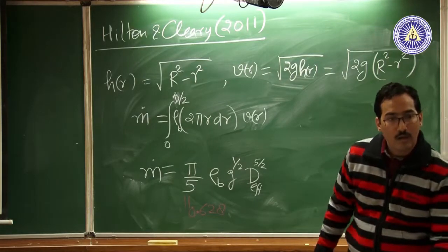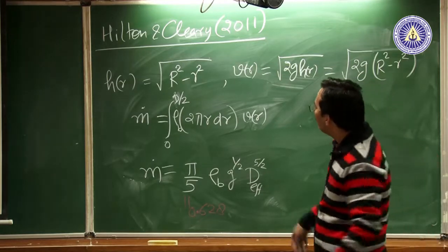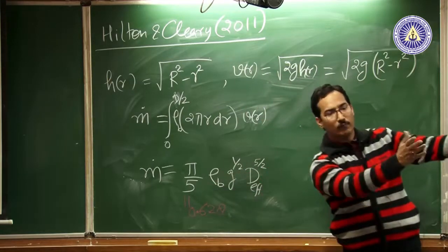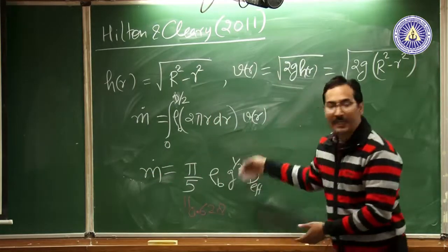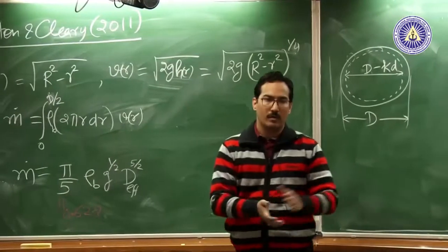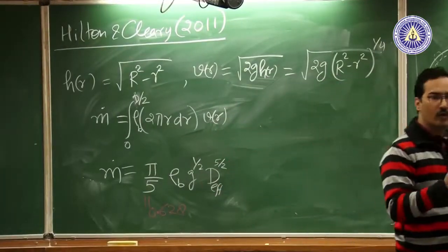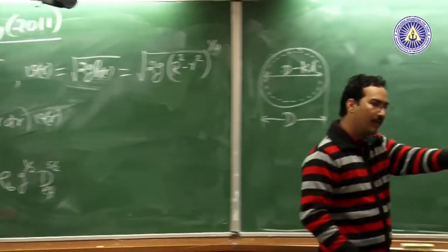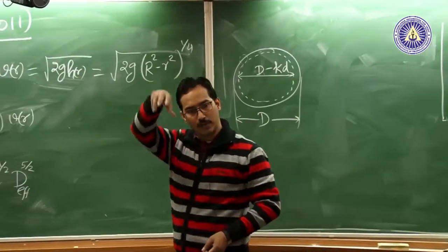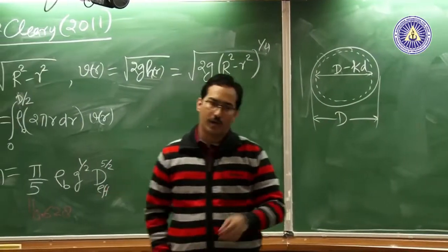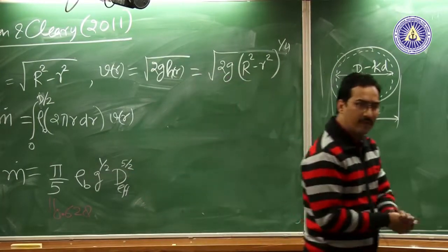Please. So are there any limits on particle diameter of this theory? Well, this theory is just trying to say why do you get that number between 0.55 and 0.65, that's it. The limit is in the experiment itself. Grain size cannot be greater than d by 6. You will start getting intermittent flow. Your flow will not be continuous. In other words, if I had a slightly coarser sand in this box, you will not see it flowing despite my tilting it up, or it may flow for some time and it will stop again. What if finer? Finer will flow.